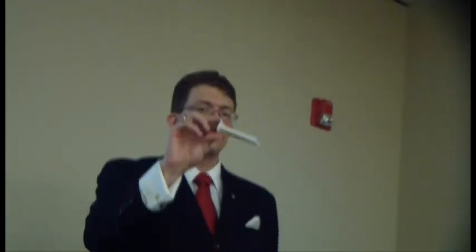Now, the detail you can see in there is pretty picky, and we wanted to make sure that everything fits just right. But we didn't want to waste a lot of money on 3D printing the entire model as an STL. So what we did was we made just that small sample piece, and here it is. This is the actual sample that we made. It's fused deposition modeling, which is almost full strength ABS. And we basically proved that it could work.